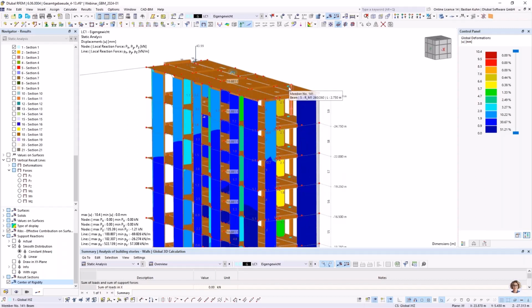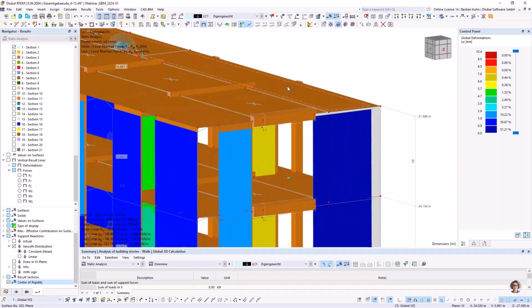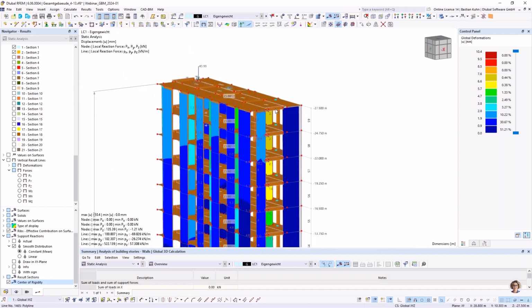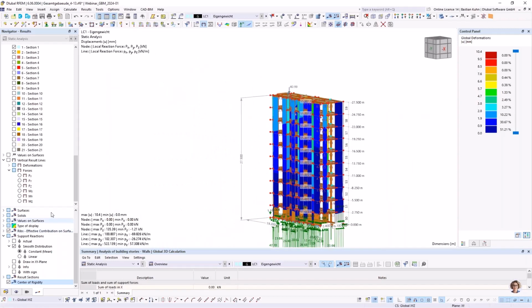And this is actually something when you are doing a dynamic analysis, which would also be possible with this add-on. It would regard your eigenvalue analysis due to the response spectrum method, and you would get the force in every story, and you could regard torsional effects by introducing load on the stiffness center, because if you introduce the load on this point via the eccentricity to the mass point, you can regard torsional behavior of the structure perfectly. You have that in each story, here, here, and here. Okay, this is one of the advantages of the building model.